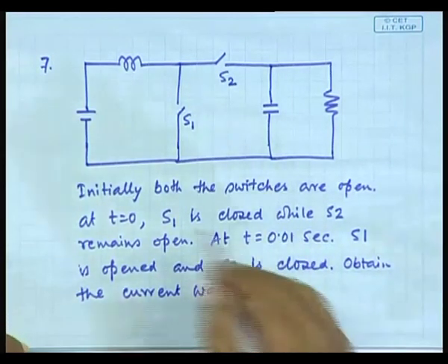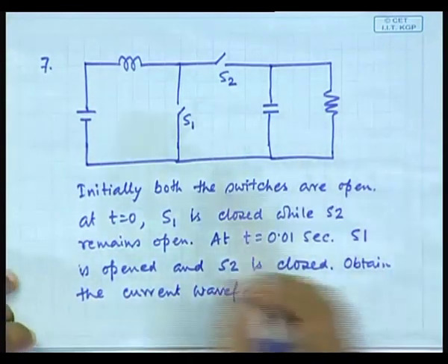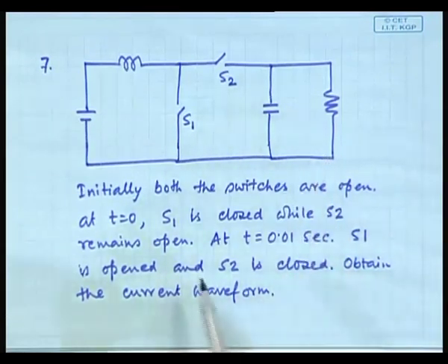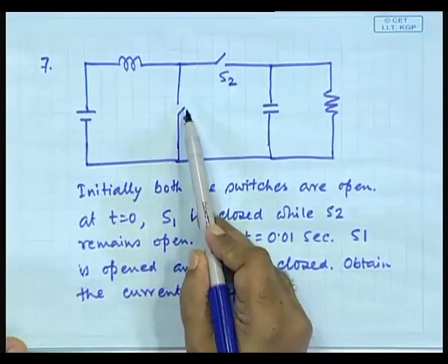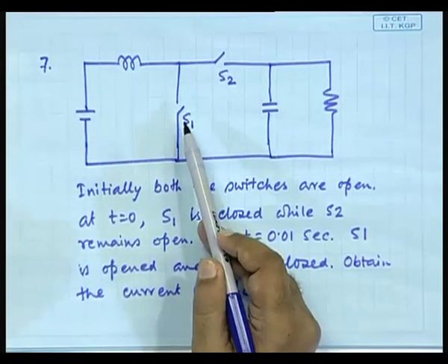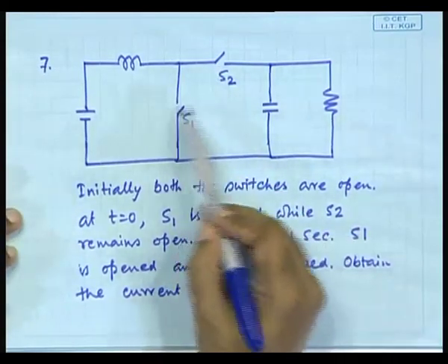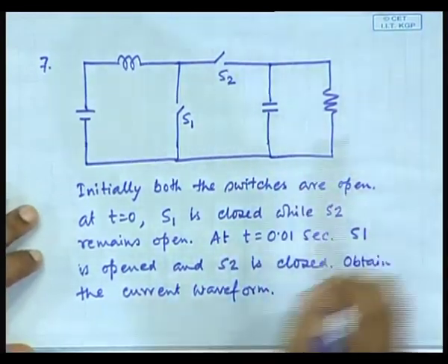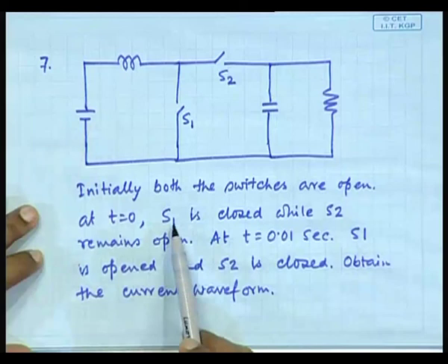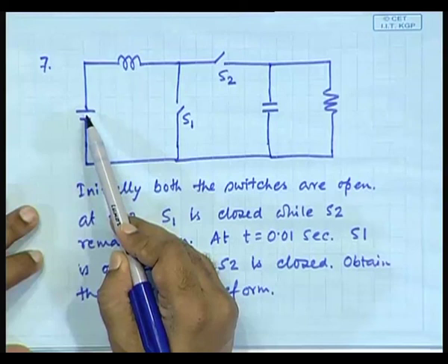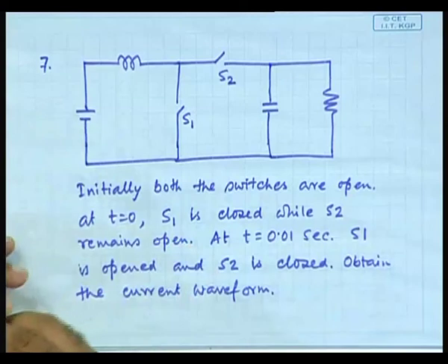Those who have read a bit of power electronics would immediately realize that this is nothing but the boost converter. So when we talk about S1 being open, normally this is realized by means of an independent switch, a MOSFET in general, and this is a diode. So whenever there is a switching on and off, this operates complementarily. So initially what is the circuit? When S1 is closed, it is only this. What will be the waveform then?